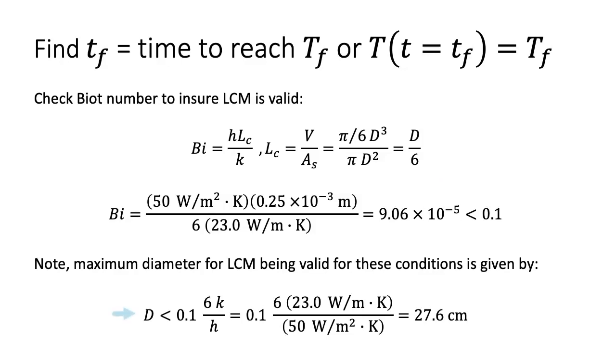Before continuing, just for fun, we solve for the largest diameter for which the lumped capacitance method would be valid. For these conditions, our bead can be up to 27.6 centimeters in diameter, which is quite a large bead.